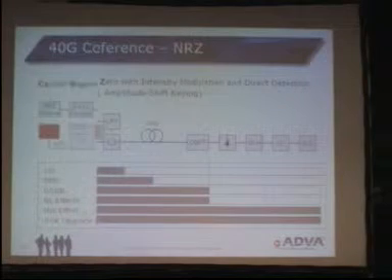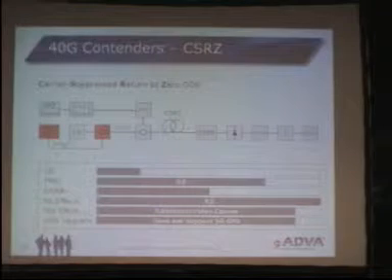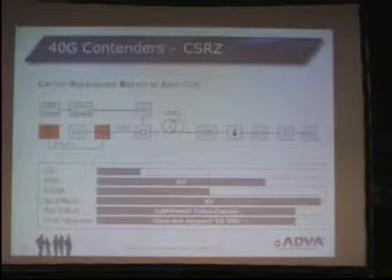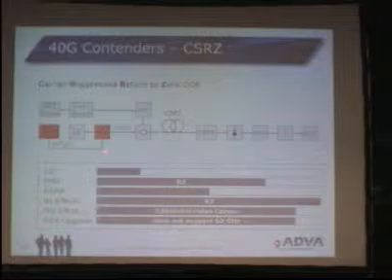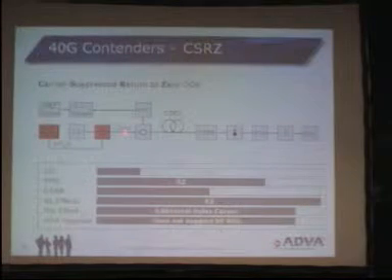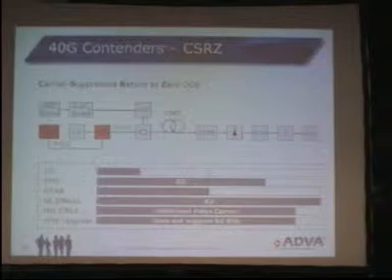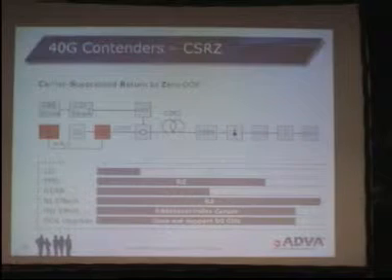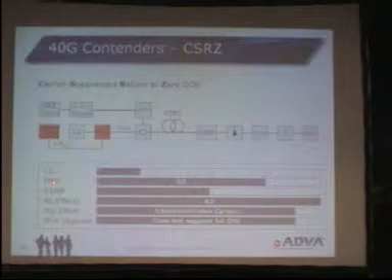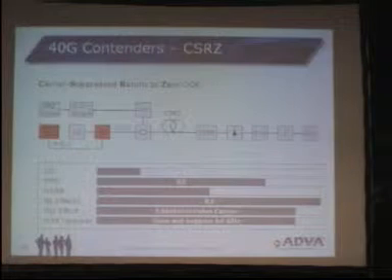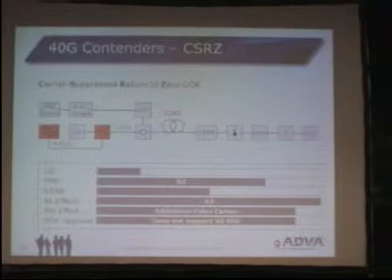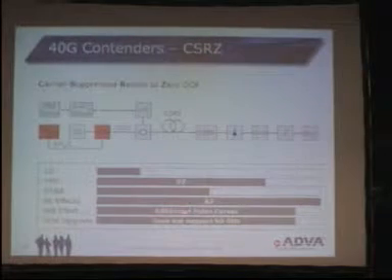So let's have a look at the contenders, as I call them. This is carrier suppressed return to zero, existing modulation scheme for 40 gig. Here we have the addition of the carrier suppression, simply by means of another external modulator, which is used as a pulse carver for proper pulse carving. And we can see chromatic dispersion, no big change. PMD, the allowance massively increased. And nonlinear effects as well. And these two only decreased a little bit. Hardware effort, that's clear because we have an additional component.